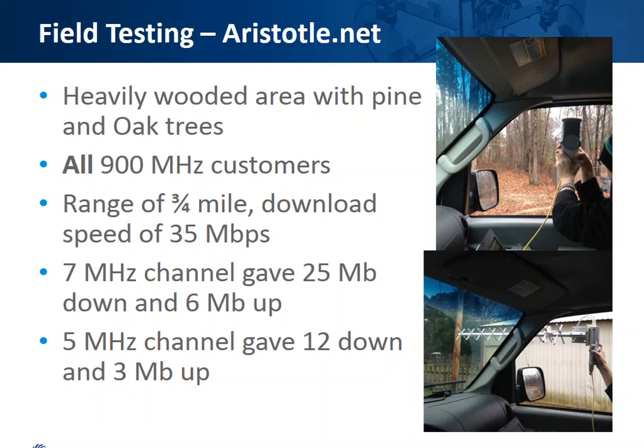So we got the beta test from Cambium, and we took it and put it on the south side of the tower where we have most of our customers. We went about 3/4 mile away, and I did a speed test and was pulling 35 down and like 7 up on a 7 megahertz channel. We were like, wow, that is amazing. And then I tested on the 5 megahertz channel, the 7 megahertz channel and the 10 megahertz channel. 20 was completely out of the question because of the interference. But the speeds that we saw with non-line of sight were amazing.